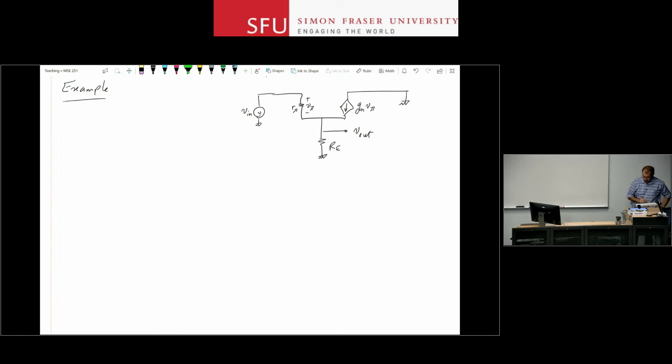Now let's go and analyze this circuit. I can use KVL or KCL. Let's just use KCL for now. So KCL says, if I pick this node for my analysis, which is basically the same as this node, right? It says that this current plus this current plus this current should add up to 0. So let's call them I1, I2, I3. So I1 plus I2 plus I3 should be 0. I3 is leaving the node, and I1 and I2 are entering the node. So I1 and I2, the currents that enter the node, should be equal to I3, which is leaving the node.